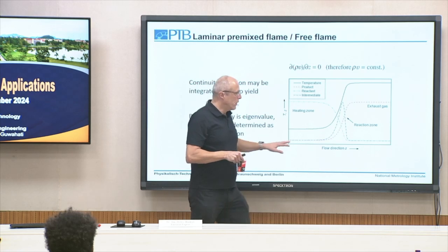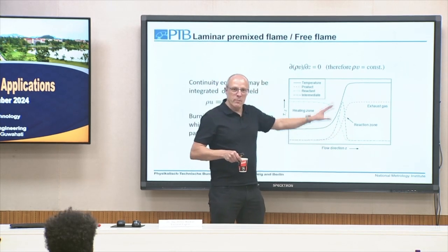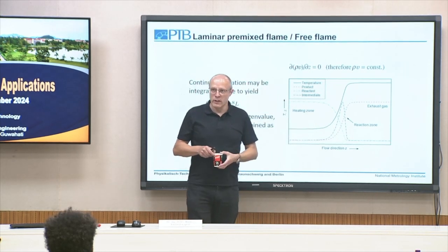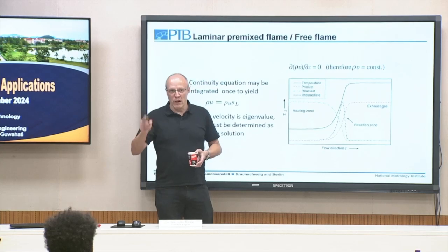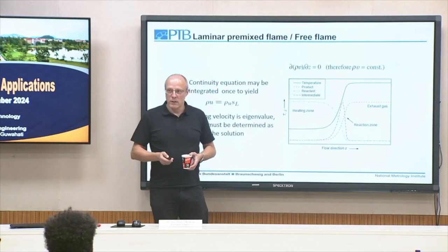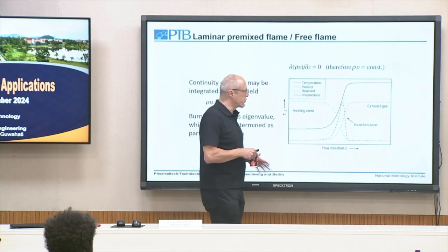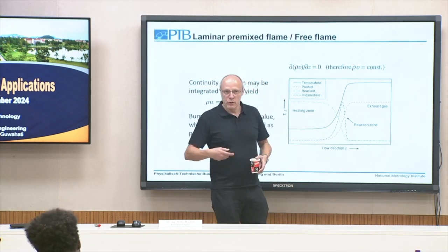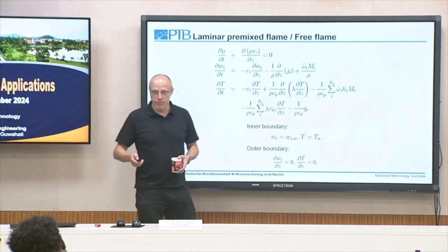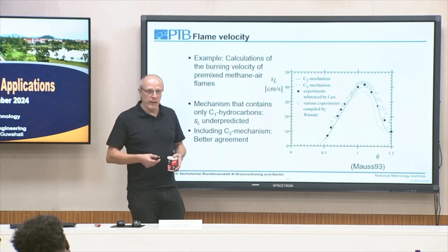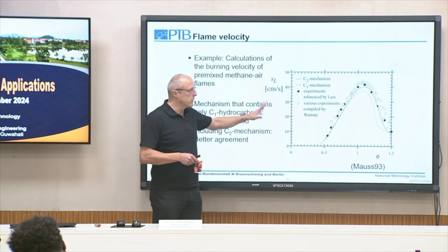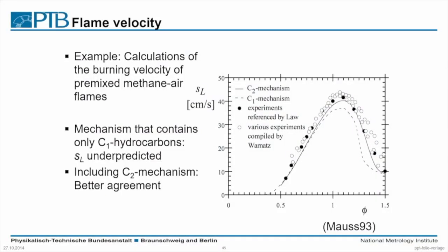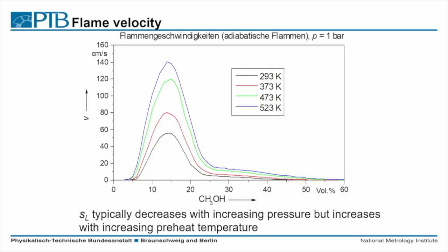If you use here 5 meters and your flame is finally 1 millimeter, the numerical system needs some time until it optimizes it. But if you start instead with 2 centimeters instead of 5 meters, you yield your solution much faster. But nevertheless, we are talking about seconds today to yield this information.